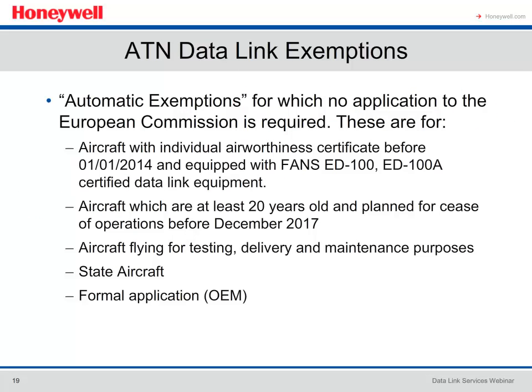Eurocontrol is allowing exemptions to the ATN mandate. As previously mentioned, aircraft equipped with FANS capability prior to January 1, 2014 are exempt from the ATN mandate. Aircraft that are at least 20 years old and will cease operations before December 2017, flight test, delivery, and maintenance flights, as well as state aircraft are also exempt from the mandate. Additionally, an aircraft type may be exempt by formal application by the aircraft manufacturer.